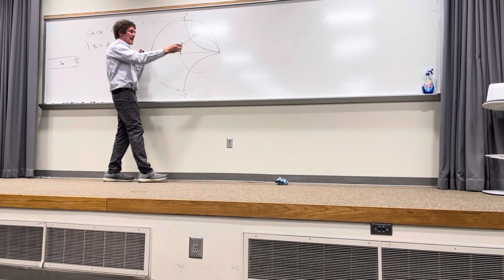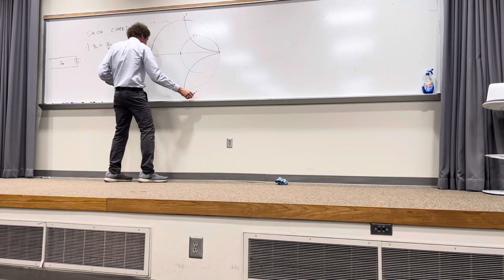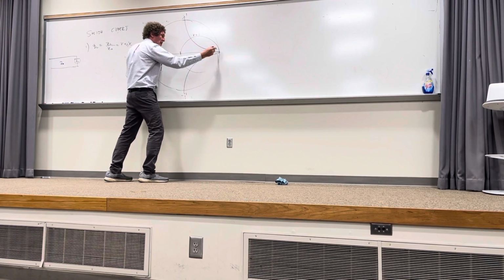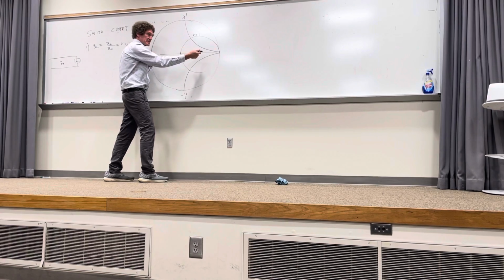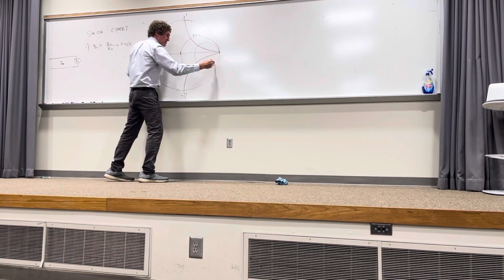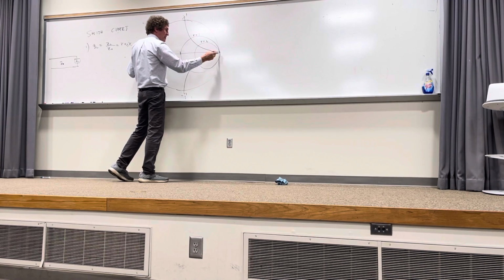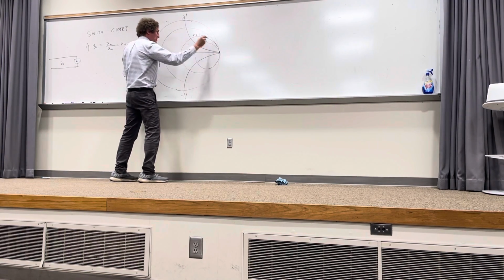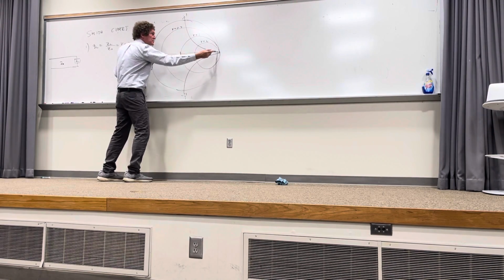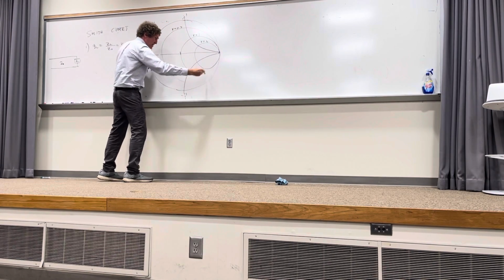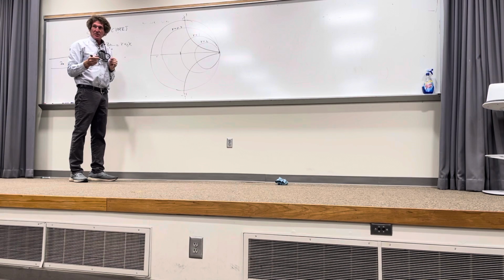Now, what you really have with the Smith chart is you have circles that are centered on this horizontal axis, same one, but they're just real values. For instance, R equals 2 is about here. R equals 0.3 is here. And R equals 0 is this big outer rim. You with me? I know it's a lot to take in, but when you do this, the way I'm showing you it, I think you'll appreciate why I'm showing you this way.